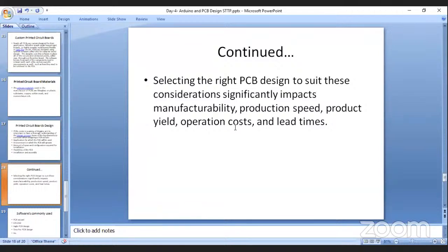If you are making, let's say, an academic project or a small mini project, you should not go for a fiberglass based PCB or epoxy PCB, that will be of high cost. You can choose a copper clad or general purpose PCB for that. It will save your money, right? Because it offers you testing purposes, whatever requirements are there, it provides those things, right?